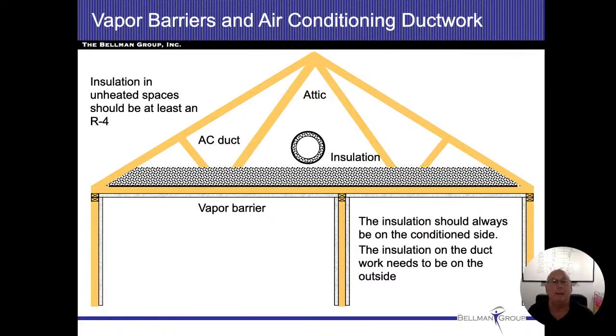Any breaks that we have in the ductwork is going to end up being heat loss. So there's a product called aeroseal right now that a lot of people are really high on. And if you want to get into energy efficiency in the homes, this does fall under our realm. So people do blower door testing, ductwork testing, and you can actually put pans and check pressures and see how much leakage is coming from these items.